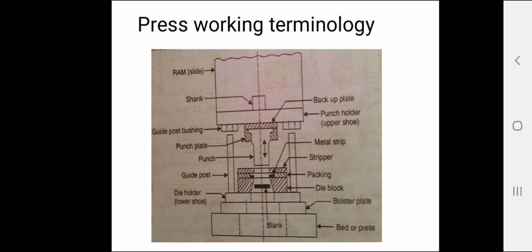For punching, blanking and trimming operations, usually a crank or eccentric type mechanical press is used. This is due to their small working strokes and high production rate. In these operations, there is a sudden release of load at the end of the cutting stroke. This sudden release of load is not advisable in a hydraulic press, so hydraulic presses are not preferred for these operations. If however they are inevitable, then some damping devices are incorporated in the press design.